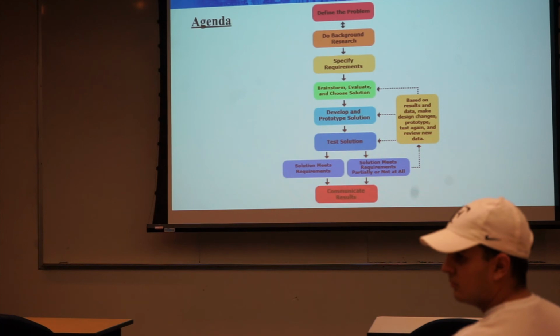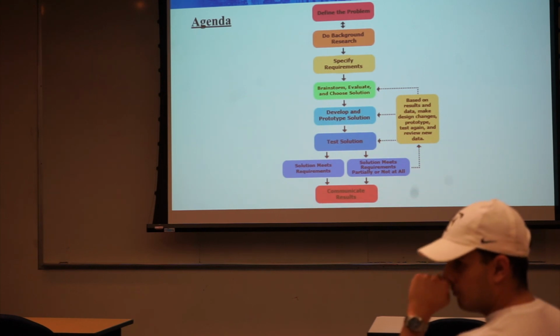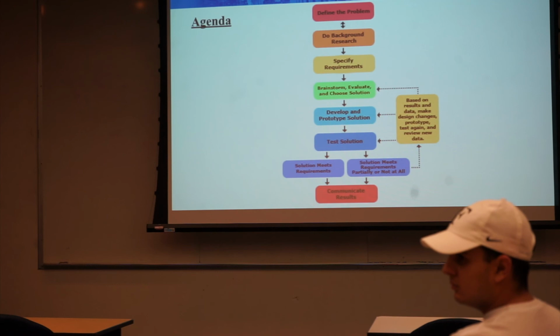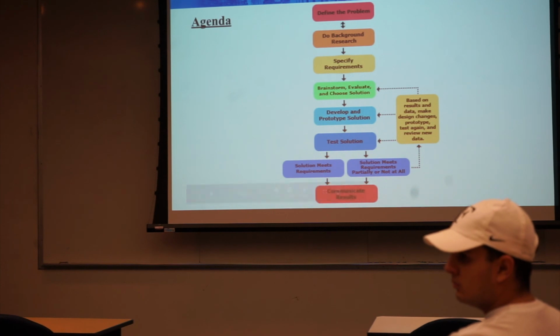I'm specifically doing torque vectoring. So it was adjusting the torque on each individual one of those motors that he was just talking about. So from there, it was how are we going to distribute that torque? Why are we doing it this way? And once you go through that logic of figuring out what you want to do with it, you realize the next step is making something to make that occur, right? So we used MATLAB to make that logic happen, converting it to C++, to C, and right now we're testing it. The process will only keep going. If something goes wrong, we're going to have to do a redesign, redo it again. But that's just the basic idea.